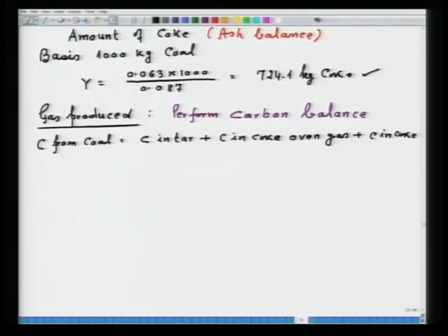You will find that carbon is being distributed in all these three components, the tar, coke oven gas and coke. Now, we should also see that we have four variables. Amounts should be known. Carbon in coal amount we know, tar amount we know, coke amount we know, percentage is also known to us. So, the fourth amount, that is carbon in coke oven gas, we do not know, but the percentage carbon that is there we know. So, we can calculate, it is very simple as that, right.